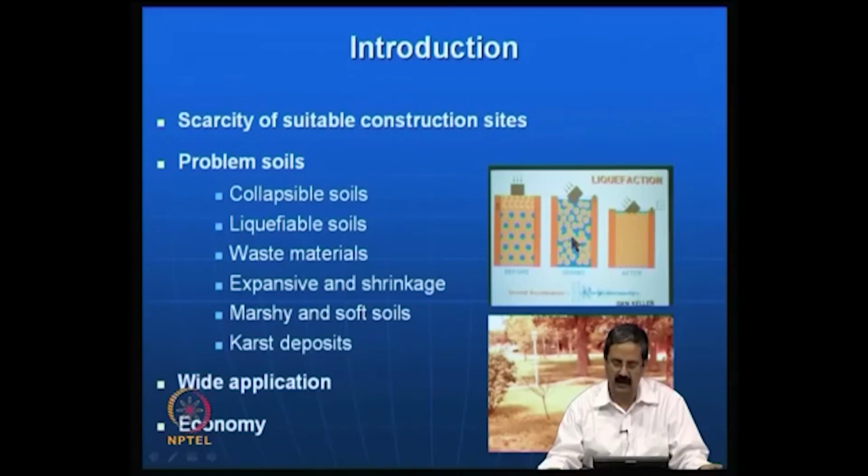We can call it a quicksand condition also, which is nothing but static liquefaction, meaning the soil behaves like a liquid when the effective stress is 0. When the effective stress is 0, the soil loses all its strength and behaves like a liquid.